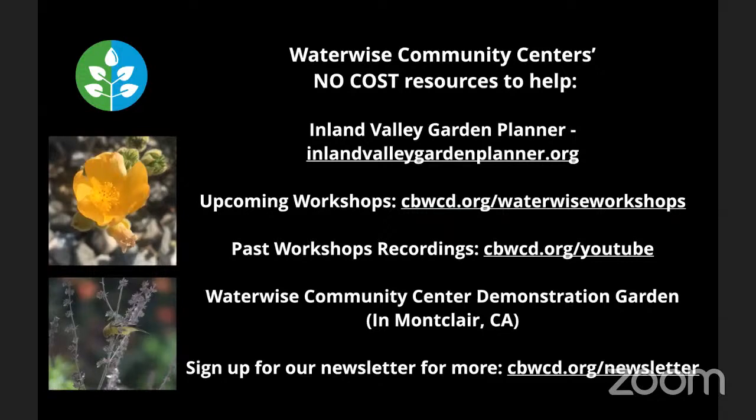And so for the areas that need different schedules, they're going to be connected to different valves. And then each different valve can be assigned to a different, what's called an irrigation schedule within your controller. So you can have a schedule in your controller for your low water plants, a schedule for your fruit trees, and a schedule for your vegetable gardens. And all of those would run off of different valves that the controller turns on the different schedules.